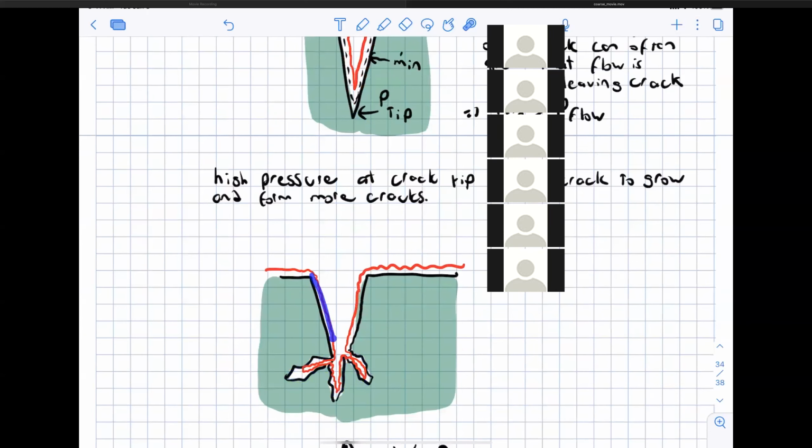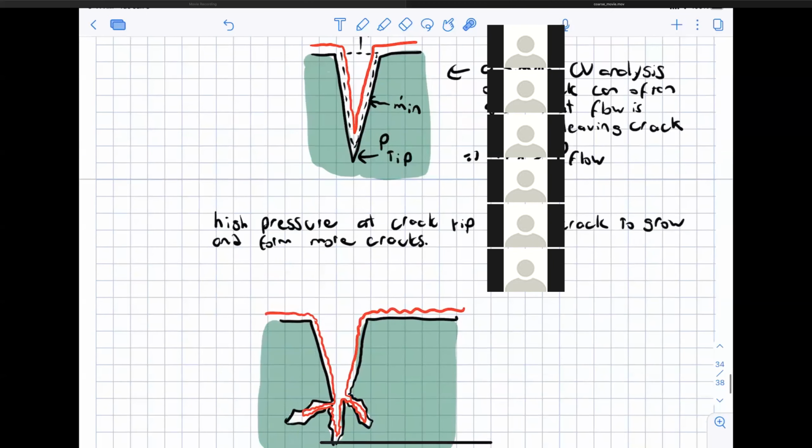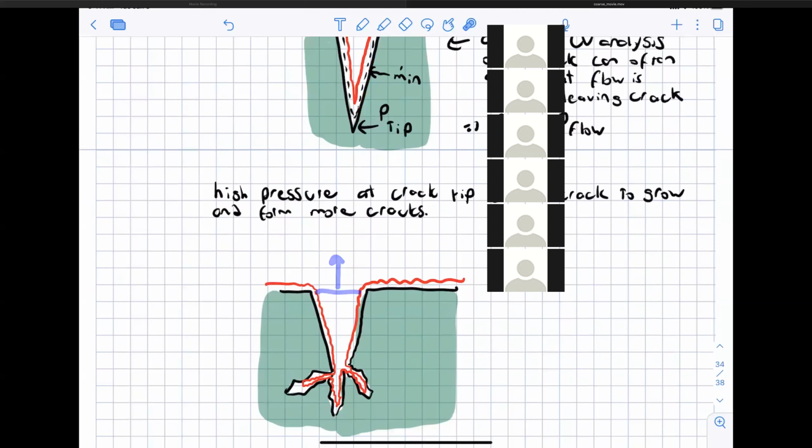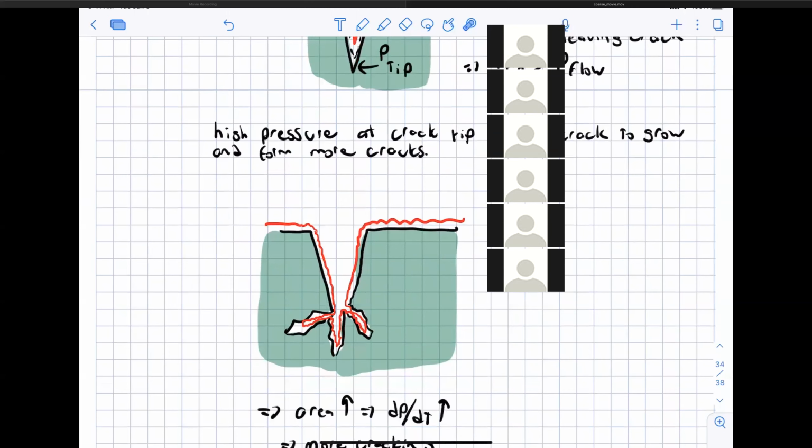Now all of a sudden, we don't just have this crack area, we have all these side cracks too, and the burning area goes way up. We haven't increased the exit geometry very much, so we have all this mass that needs to go out, and our only choice again is to increase the gas phase density, which again requires an increase of pressure.